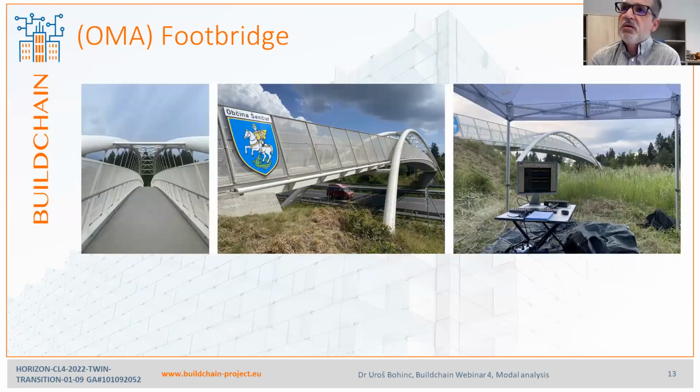So the second example that I wanted to share with you was a measurement of a footbridge, which we did last summer. Since this structure is obviously quite big, it was not possible to excite it with the modal hammer. So we had to rely on excitations from the environment. Usually the traffic was just good enough for this excitation.